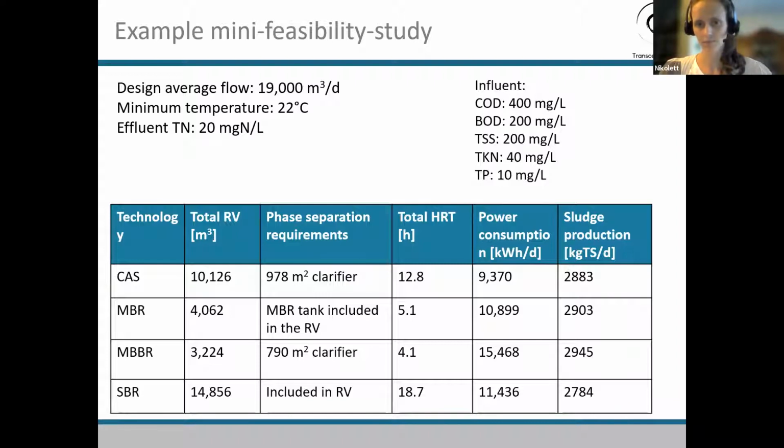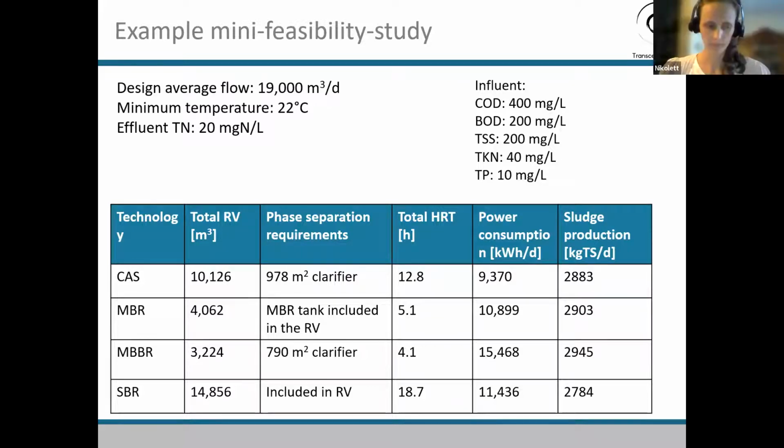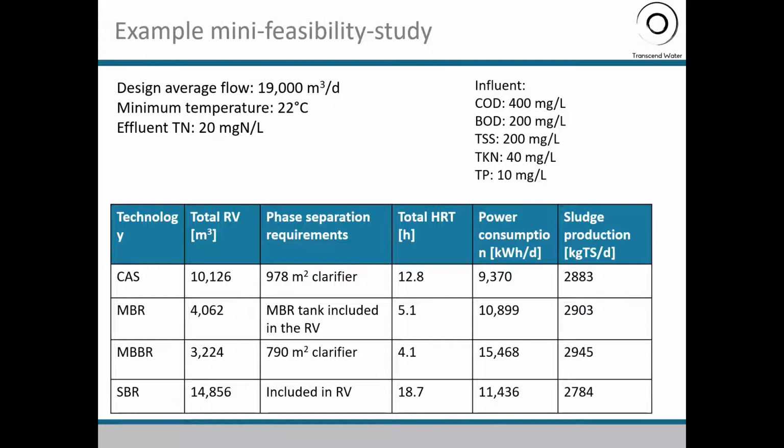Yes. And then John also had a follow-up on the sludge blanket level detector. So he said, regarding the answer that we provided, not exactly, since if the plant receives a high F/M or high load influent, you need the sludge detector to react to the higher biomass. One indicator is higher MLSS, but you may need to increase the RAS.